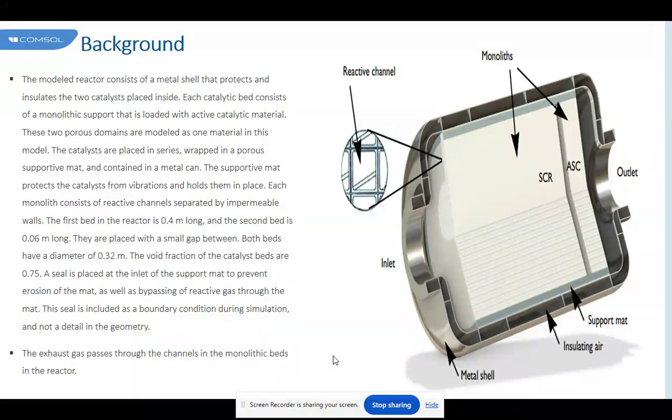Analysis of the effect of substrate on cold start time. We now present a brief analysis of the effect of the substrate materials on the cold start or heating time. As stated earlier, the substrate material can influence light-off time in two ways: through the solid conduction and propagation of the temperature front through solid heat capacitance.